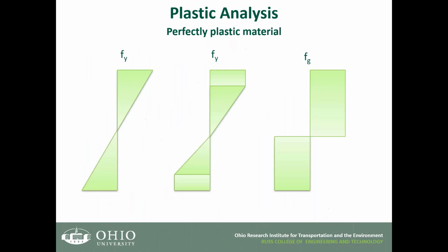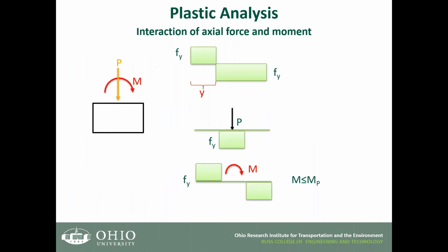So linear elastic is the first picture from the left. The second is when you load it a little bit more, you go to the plastic zone. Then when it goes completely plastic, the strain and the stresses look like those rectangles. Go ahead. You will have two parts on that one.